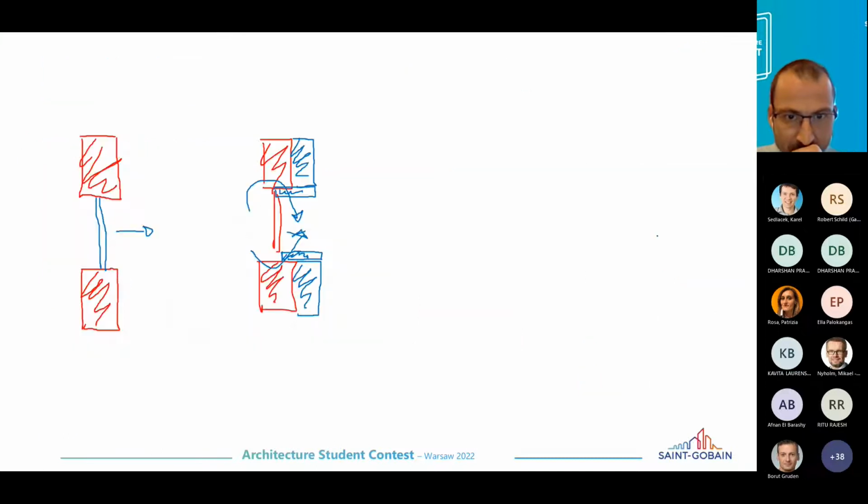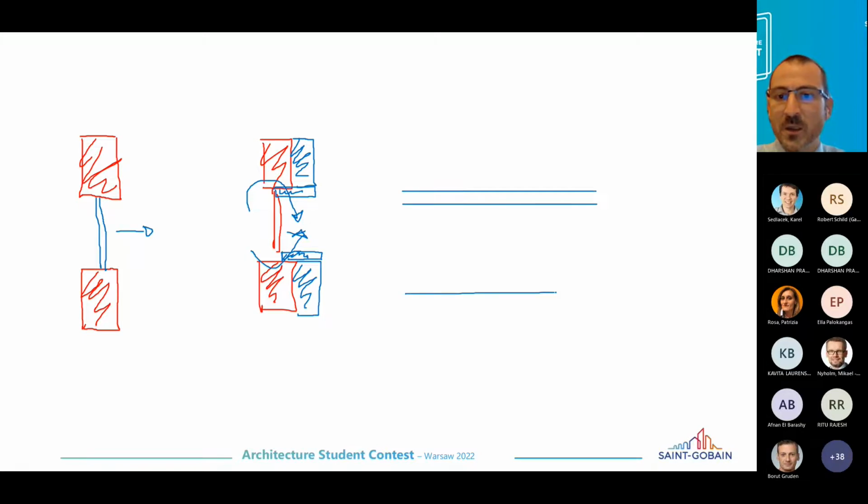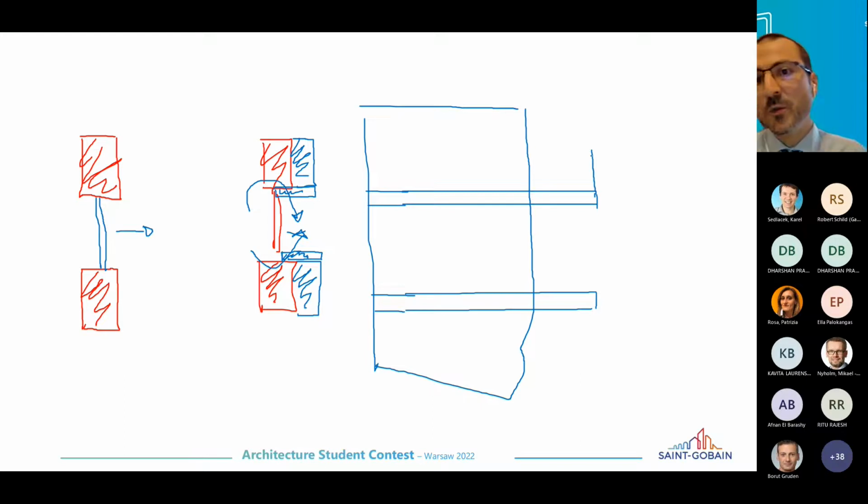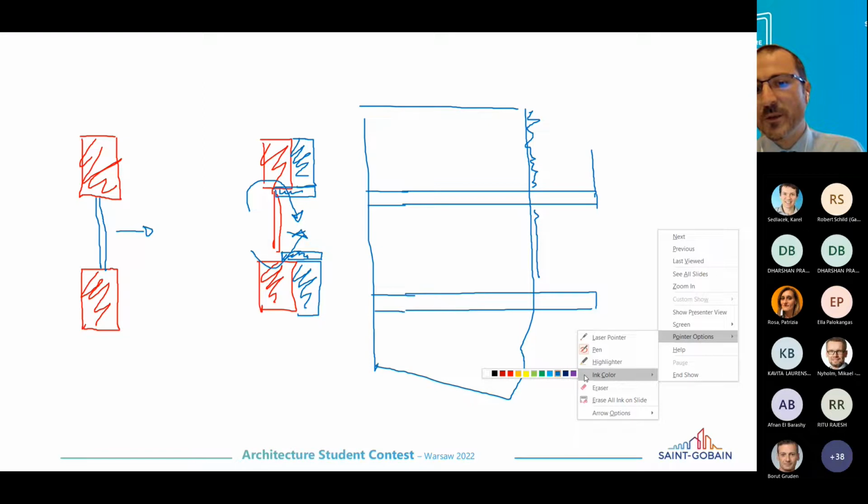And then there is another very common design, in which if you have a multi-story building, then you have the balconies, something like this. Sorry, come on. Okay, and of course the balconies are part of the floor slab. Yeah, and I'm speaking now about a hypothetical example of a renovation. You can try to insulate this part, you can insulate this part, but most of the time this one is not insulated as such. And basically this is a huge thermal bridge.